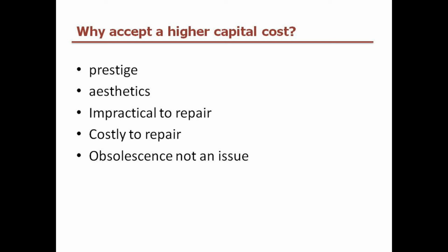Obsolescence as well: trying to keep those components of the building and, where you can, ensuring that obsolescence really isn't going to be a problem. Sometimes it is, even within 6 years, with simple components such as fire panels that there are no parts for because technology has changed. You can get around that at the initial design stage.